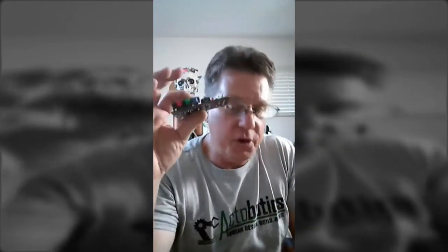chattering. If you're having chattering problems with your servos, oftentimes with mine, I try and isolate, like on Frankenstein, which is a 3-axis controller, I isolate the power supply that drives the servos, so I'm using 2 power supplies. A 12-volt power supply that drives my audio board. It's reduced down.